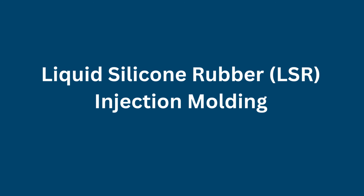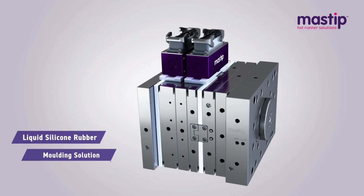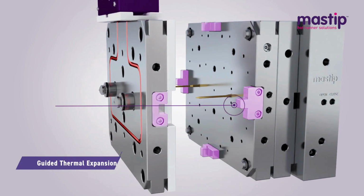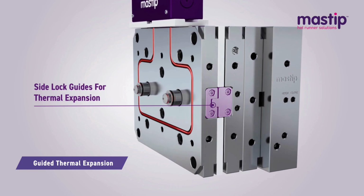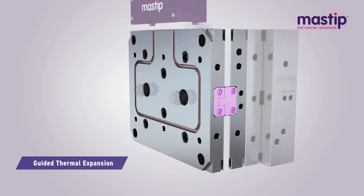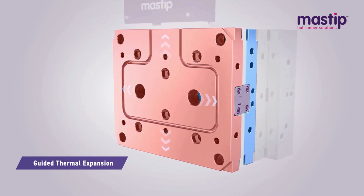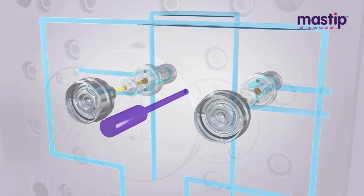Liquid silicone rubber, LSR, injection molding. Unlike reusable silicone mold casting, LSR injection molding manufactures finished silicone products directly. Two-component liquid silicone rubber is pumped from separate reservoirs into a static mixer immediately before injection into heated steel molds.